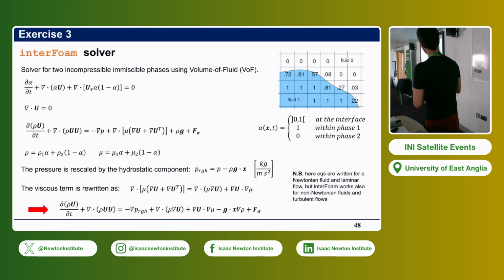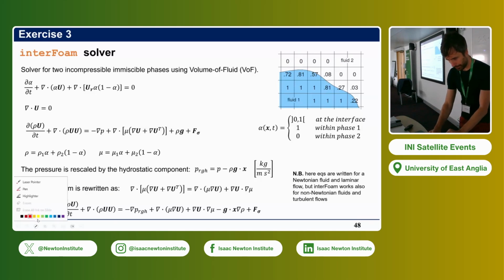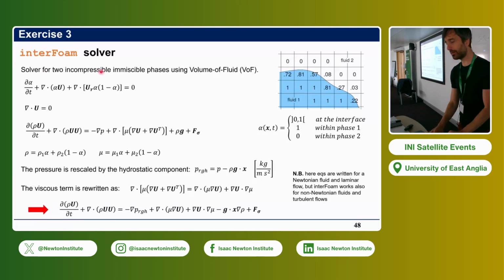So let's start with the interFoam solver. So that you can all see, I can stay here and use the laser pointer. I guess at this point, after Radu's talk yesterday, you're all familiar with the volume of fluid method, even though interFoam is an algebraic VOF solver, so it's less accurate than the geometric VOF, but it has some advantages, as I will say. interFoam is a solver for two incompressible immiscible phases using VOF.